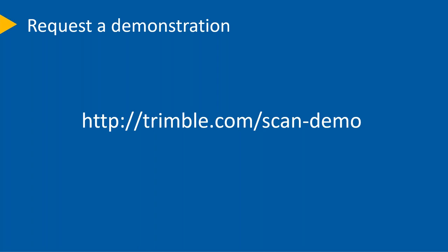All laser scanning systems, in general, will start to become less accurate the farther away you go. If you're scanning far away, that's where it would be good to look at maybe a phase-based versus a time of flight if you want to maintain that accuracy. And then also the example I gave where you can't see something sometimes. For example, if you're working in tall grass, the scan data will see the grass, but if the grass is too thick, you won't be able to see the ground. Whereas if you had a prism on a prism rod or a GPS, you could very easily go and get those ground shots.